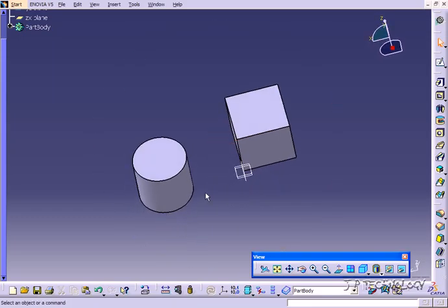So what the hole feature will do is it'll allow you to create holes, many different types of holes, without actually sketching it out or cutting and extruding and doing everything else. You're able to do all of the holes directly from the hole feature, and it gives you all the options, so it saves you some time from sketching everything and piecing together each different type of hole. So to start off, let's click hole, and let's click a face we want to put a hole